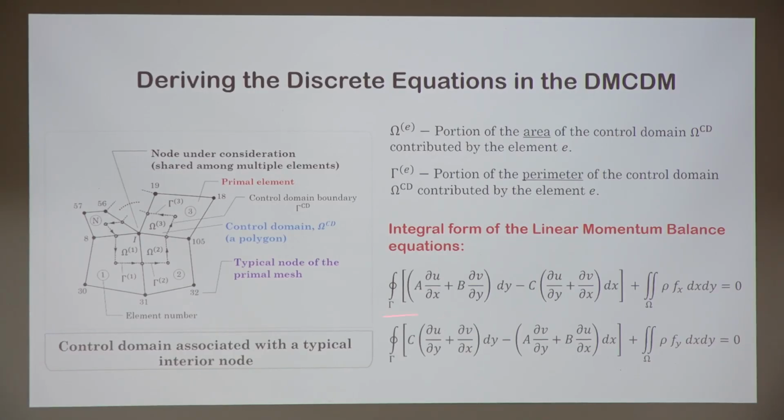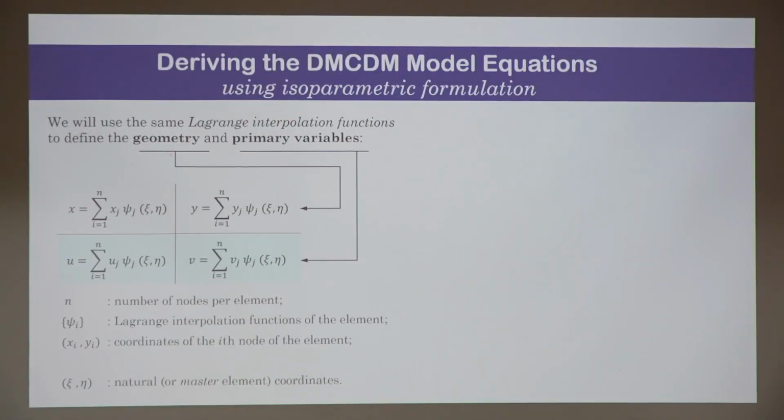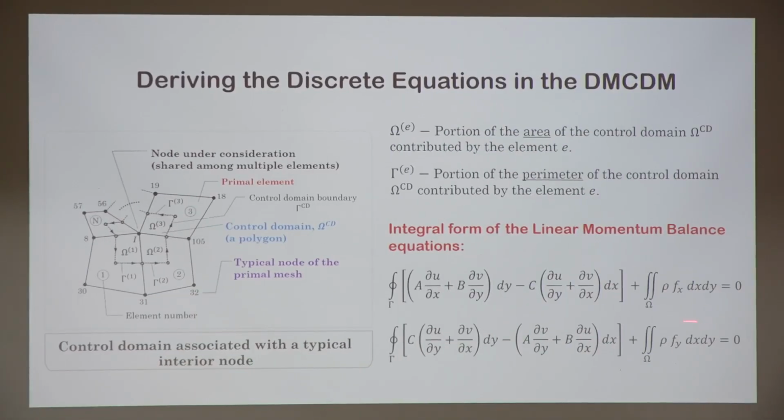So you can see the two elasticity equations written just as integral statements on the boundary of the control domain, not the boundary of the element, rather the control domain. And so, by the way, let me go back here. See, in many real world problems, there are no body forces. So these integrals, even though I put them there for completeness, we don't really have body forces, unless you are taking some gravitational force or something. But if it is there, no problem. You just evaluate the integrals using numerical integration.